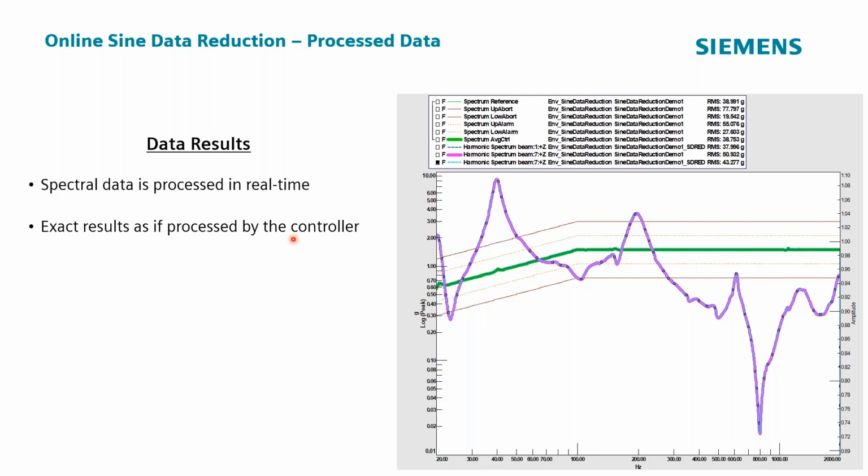If you're just doing typical auto power spectra, which is a block by block kind of method in the standard analyzer, you're not really going to get the same result from a sweeping sine wave that you would in the controller, because of the way that the controller actually works: okay, we know what frequency we're at, so we're going to plot an amplitude where that frequency is.